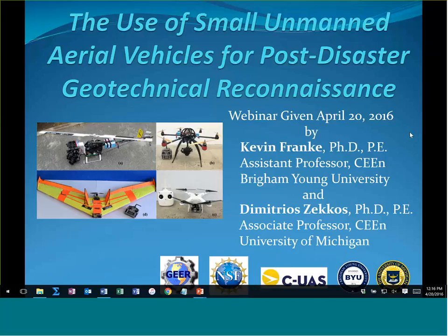So that's a very good question. The assumption that structure from motion makes when it creates a model is that the environment that you are imaging is static and not moving. Anything that moves, if you try to process that as one model, it will be removed from the processing. And so if whatever it is that you're imaging has changed in any way from time A to time B, then your model is not going to be good quality.